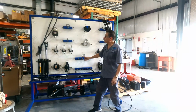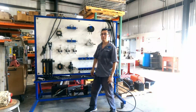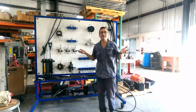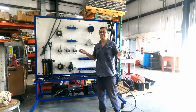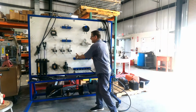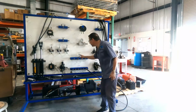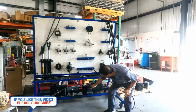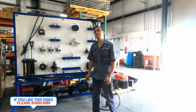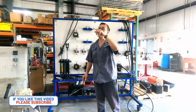From this one, I am going to activate actuators or motors, any hydraulic equipment that I want. How many? In this particular case, 4, but I can install a bigger manifold. The pressure here depends on the pressure produced by the pump, and that is the pressure that we calculated yesterday.